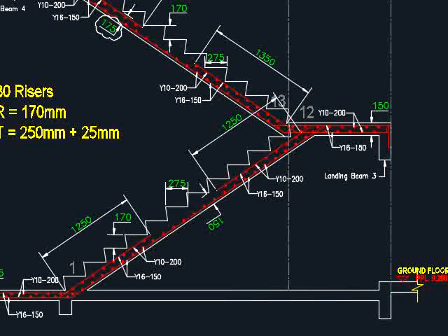It is possible for you to design as a cantilever, just that you need to be extra careful with the design. And the good thing about a simply supported staircase is that the amount of reinforcement bar is not that much. You don't have to go for a high level of conservativeness. And normally the spans of the landing beam are relatively short, which is governed by the width of the staircase. I would say that that would be an economical design.